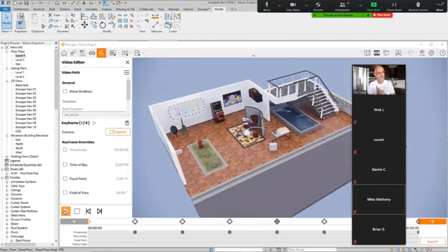Well, if you've got your XML files, if you export them individually, you can actually copy and paste, just create one new master XML file, and you can create one long camera sequence. You'll just have to go back and rename or renumber the keyframes because they start with 0, and obviously each sequence is going to start with 0, so you have to modify that. And then you'll have to modify the timestamp individually for the cameras so that they make sense.